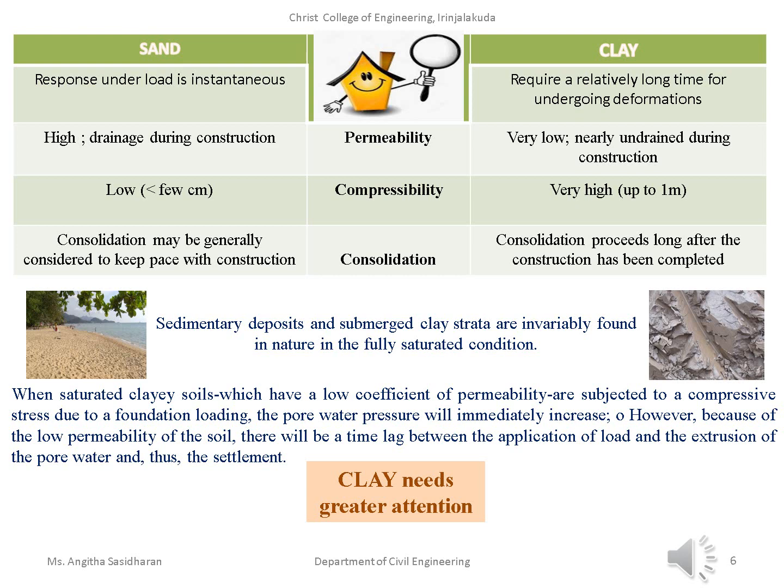Now, considering the major types of soil, sand or clay, how is the difference coming? If you are going to make a building over a particular type of soil, the building demands that you have a view of the characteristics of the soil there. In a sandy soil, the response under the load will be very instantaneous. The response will be very quick for sand.